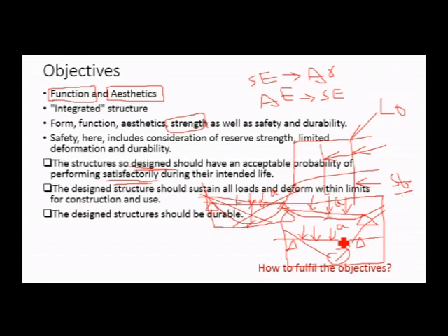For example, if there is RCC or reinforced cement concrete, after 100 years there may be some creep or some deformation or deflection due to its own weight. So that has to be considered at the time of design, and separate checks for durability are needed for the steel reinforcement and concrete as well, and this will avoid the problem of frequent repairing of the structure.